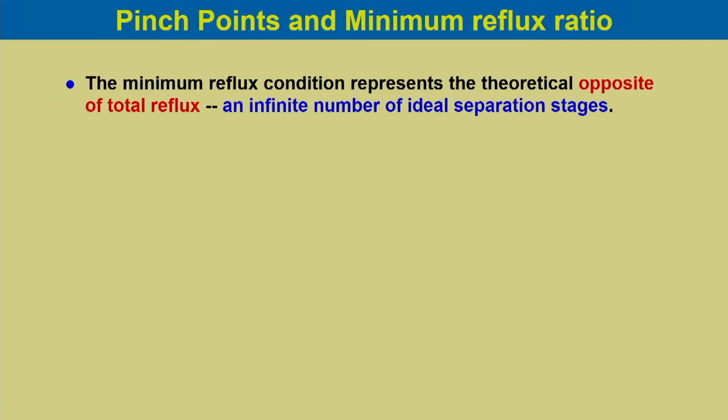line in the stripping section as well as in the rectifying section lie on the 45-degree diagonal of the equilibrium diagram. So, then the distance between the equilibrium curve and the 45-degree diagonal becomes maximum. If we draw the number of stages required for the separation under total reflux, we obtain the minimum number of trays required for the separation for a given job.